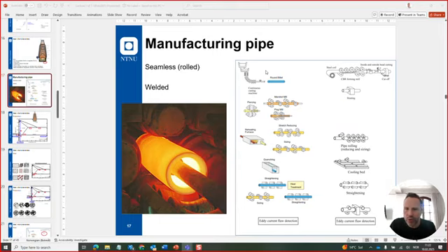There's also work to get the right size of the pipe, the right wall thickness, and also straightening the pipe, sizing and straightening. And then, as we are doing these things, we are doing what we call work hardening, and we remember the graph of the stress-strain curve, that we are going up until the point where the steel is being deformed into the shape that we actually want.